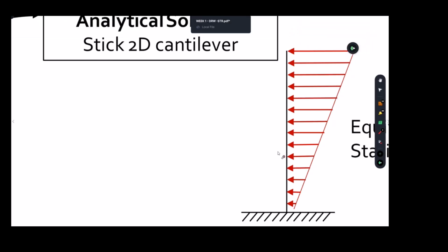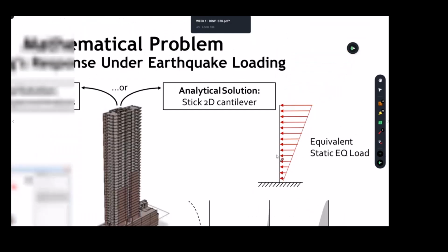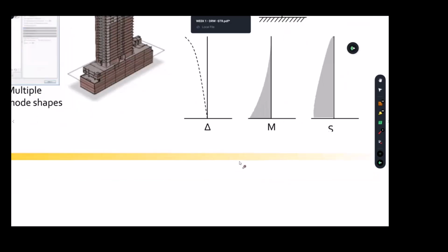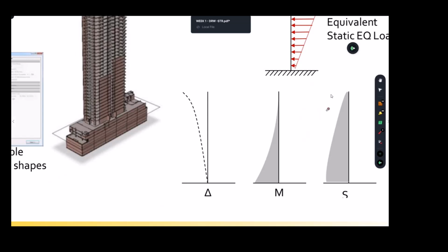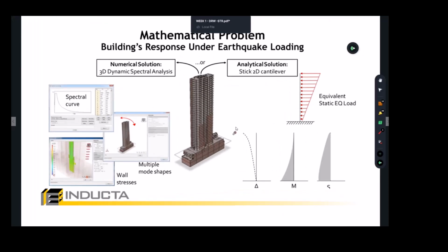They have all been studied on different sheets, by hand or whatever they used, and then they fed it to Space Gass or ETABS. Then they asked it to consider some harmonic excitations or some spectrum analysis, and then they ended up determining the deflection of the building, the moment of flexure on the building, and shear on the building. Perfect, job done. So it is possible, right?